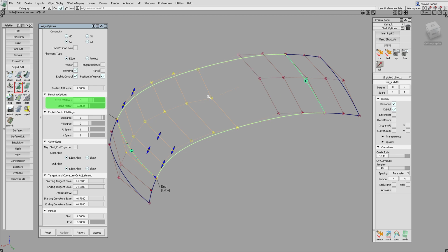But the blend doesn't look very good. Again, there's a bit of a disjoint between that end and this end. And that's where the blend factor comes in. But if we're trying to use blend and keeping continuity at one end, then we need to change the blend factor value, usually to 1. And that will give us a more progressive blend from one end to the other.